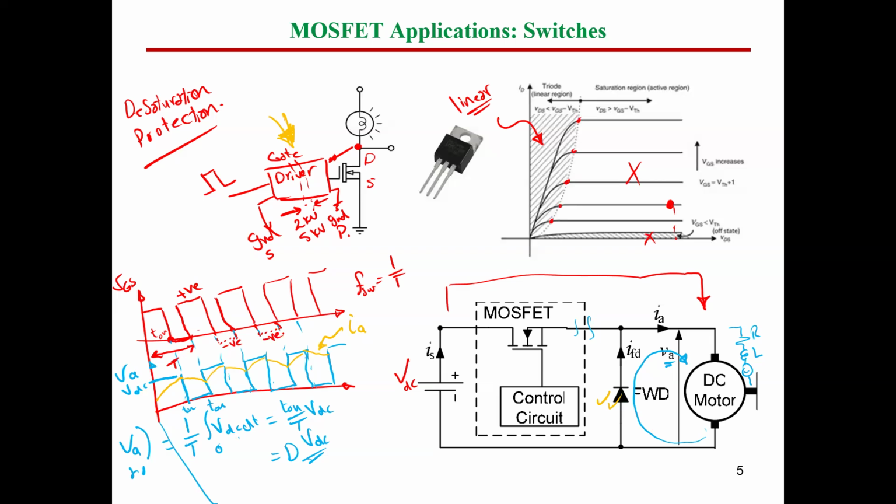Let me give you an example in numbers. For instance, the gate driver can support positive and negative, and it should be written in the datasheet of the gate driver, like plus 20 to minus 20. So it can support a transition of 40 volt, for instance. So what you can do is have, for instance, a gate voltage of plus 20 and minus 5.